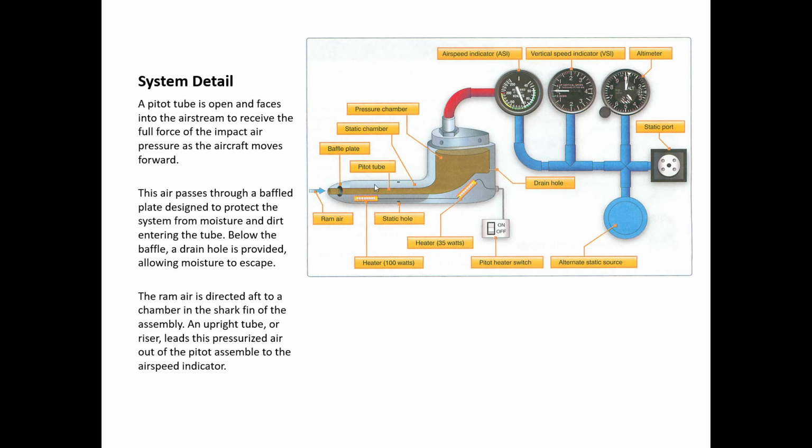There's a static hole. Where's the little drain hole? It's way here in the back. Especially with the ram air coming in, any moisture is going to be driven into this little corner. So that's where they place the drain hole.